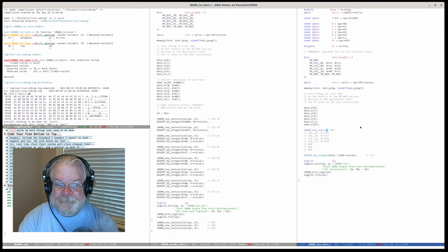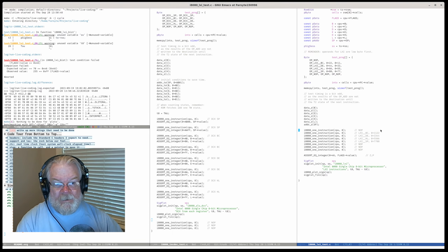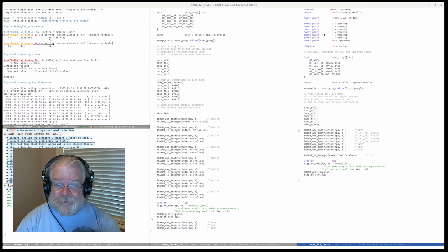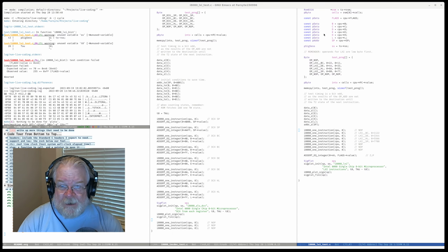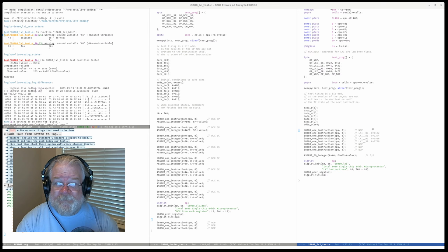The 8080 instruction. So the LXI instruction, let's make sure it does not modify any flags. It obviously shouldn't. This data is not going through the ALU. But I'm going to bring up the definition of it really quick. I haven't turned on the PDF onto OBS, but LXI, where did you go?